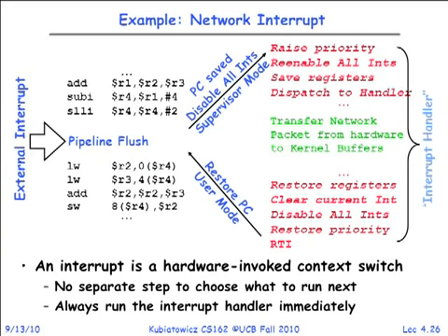Well, I don't want to get too in-depth with this, but suppose that some external event happens, and as part of this, we schedule a software interrupt by setting some bit. But in this code we're at a higher level of interrupt, so that software interrupt is being ignored. And then sometime we lower the interrupt priority level so that the software interrupt can be taken. So often the software interrupt is a way of deferring an interrupt until the priority gets low enough. But again, that's too much information, but you can take that away with you. Any other questions? They're good questions, by the way, so you guys are clearly thinking.